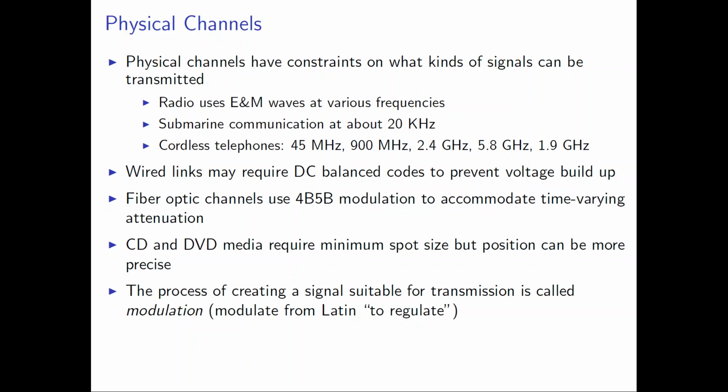So what modulation does is change the amplitude of this electromagnetic signal based on the data bits, zeros and ones. The electromagnetic signal can easily propagate through air. Since you cannot send the data bits directly through the air, you just change the properties. What do I mean by the properties? The amplitude of the sine, the phase of the sine, the frequency of the sine, according to the data bits, zeros and ones.